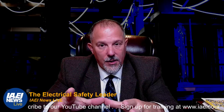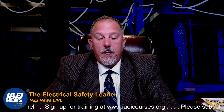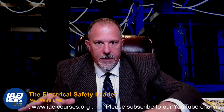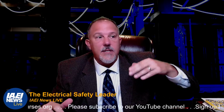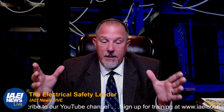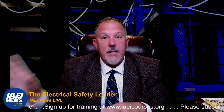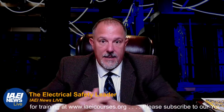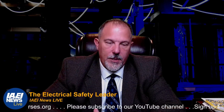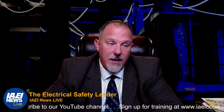After talking, hopefully you got something out of series ratings. Remember that a series rated solution is 100% rated solutions. You're going to take that route when you want to try to save some money on conductor. But don't forget, the equipment is going to be different. The panel board, the structure, the circuit breaker. Now, if you're in medium voltage equipment, don't worry about it. Big assemblies, low voltage assemblies, you're already 100% rated. But the bulk of what we do is in molded case circuit breakers, fusible switches, things of that nature. All of that stuff is not 100% rated.